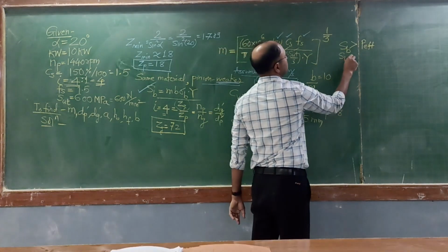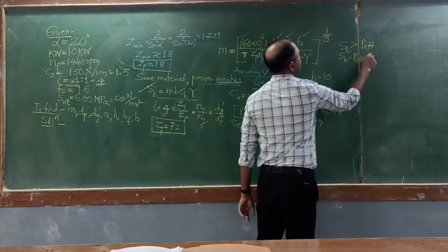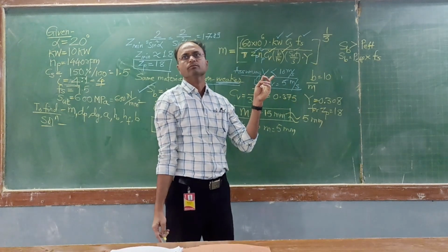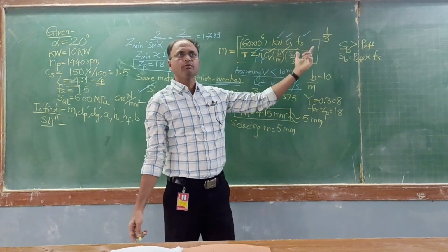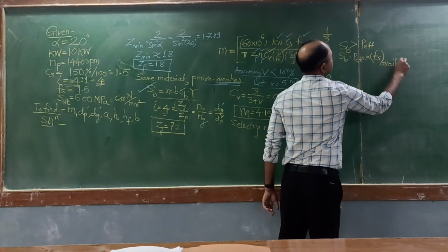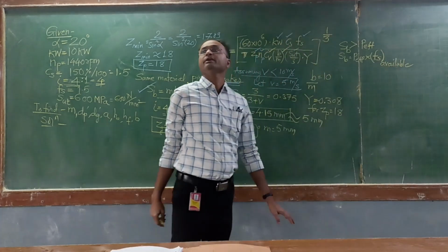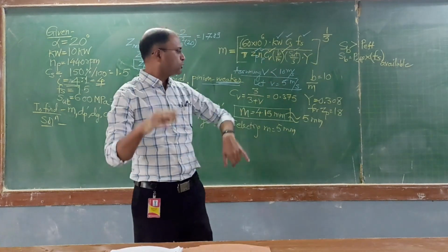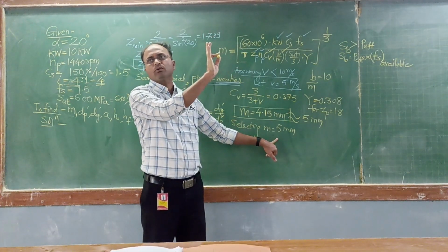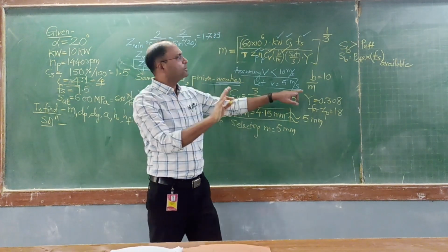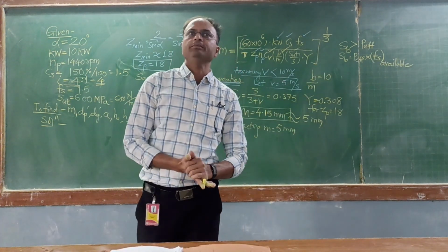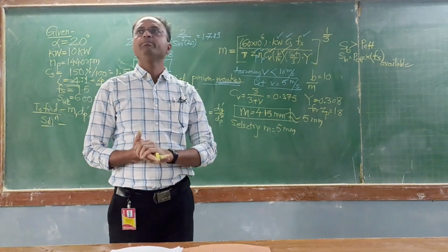So SB is equal to P effective into factor of safety. This equation was given to you. Now this is not the assumed factor of safety. Whatever we get by using this is called the available factor of safety. That means if you go by 5 as your module, what will be the available factor of safety? That we have to find out. Is it understood? So now first we have to find SB, that is beam strength. So calculating beam strength.